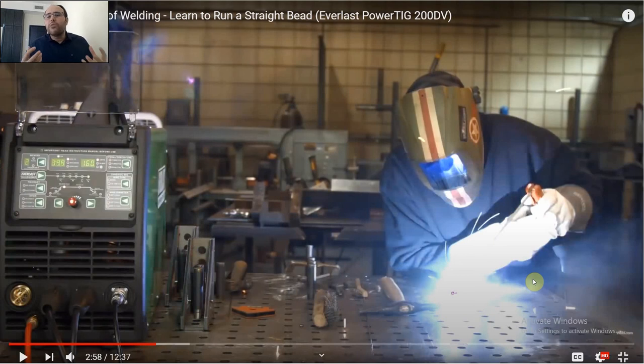This energy will be converted into heat that is big enough to melt both the metal surface and the electrode, which works as a filler in that case. So this is the theory, the concept behind the arc welding process, how it works. We depend on generating electricity and generating heat by electricity. How? Simply, we first touch the surface of the metal to close the circuit, then we separate the electrode from the surface, producing a small gap. This gap should be small enough.